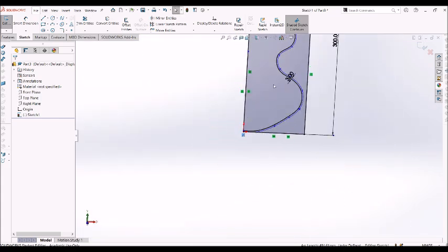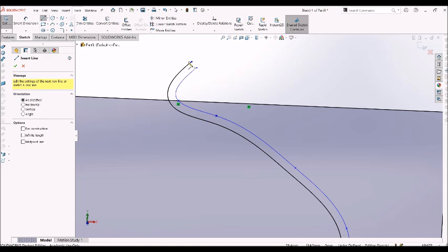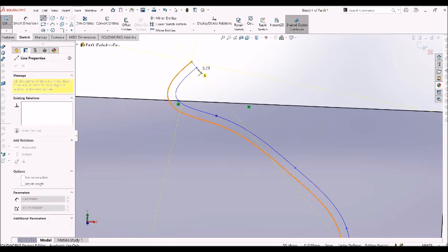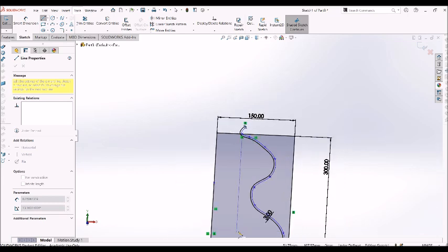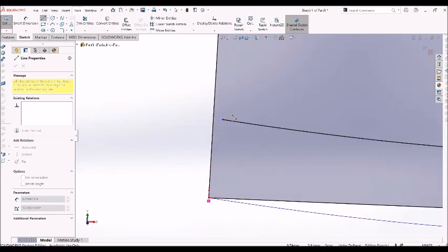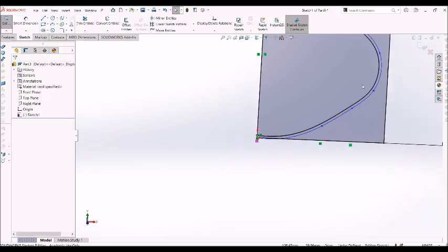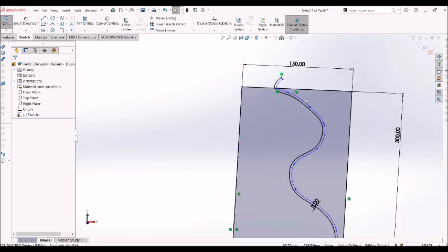And what that means is we need to draw a little line between these two lines to join them up. So if you think of a closed entity as a complete shape, we're closed up there, and we go down to the other side. And we're not closed up down here yet. So I'm going to join it to this line here to close it up. So now our sketch should be a closed entity.